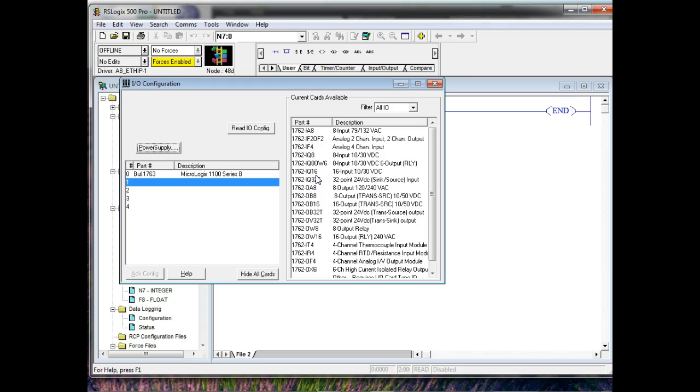Now the 1100 that some of y'all have in the little suitcase, that is a true fixed PLC. And the big disadvantage of a fixed PLC is what? But they're very cheap, but you get what you pay for. So the 1000s that we have, those are fixed PLCs. Are we okay? Make sense? Okay. And then this would be what you put in beside that. So this guy right here can handle up to 3 additional modules. The little Micrologix 1200 we have can have 8 of them out there on the right hand side.